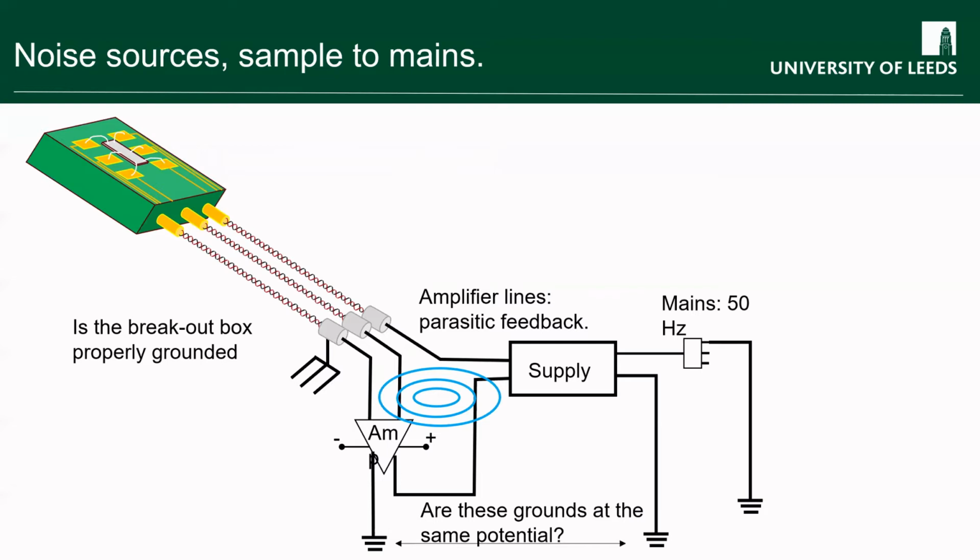So again, one of the problems you can have is your measurement electronics can naturally produce some oscillating currents. Those can then be feeding noise into the experiment, which you're then picking up as you're trying to measure. So you need to think about whether you need to be filtering the signal lines to get rid of these parasitic effects, to stop using additional feedback. You can get coupling within your electronics boxes. So, for example, you could get capacitive or inductive pickup from inside your electronics that you need to check you don't have.